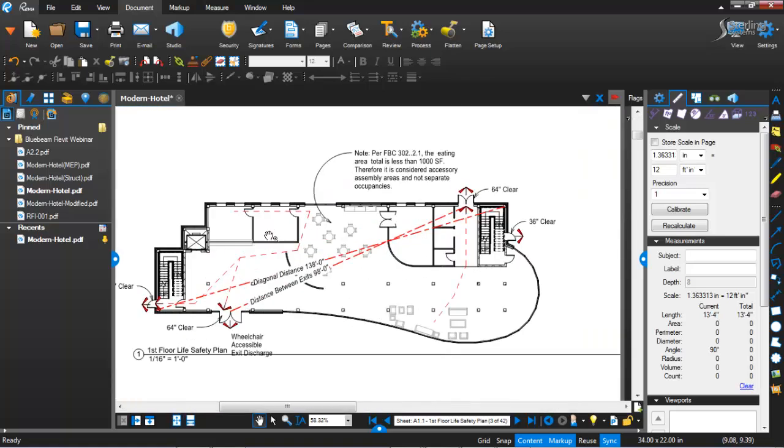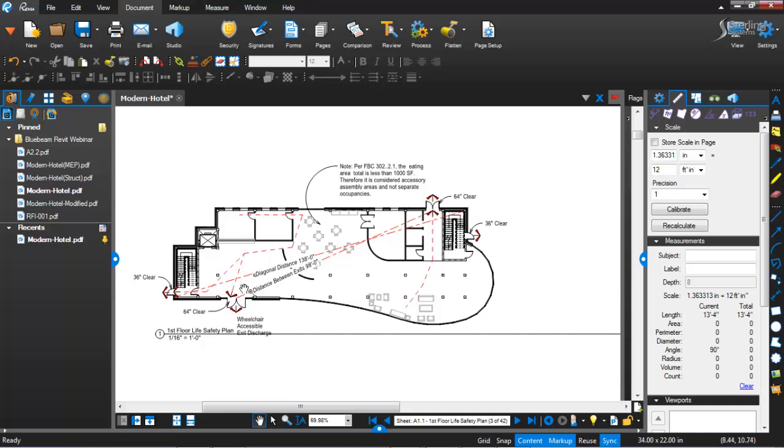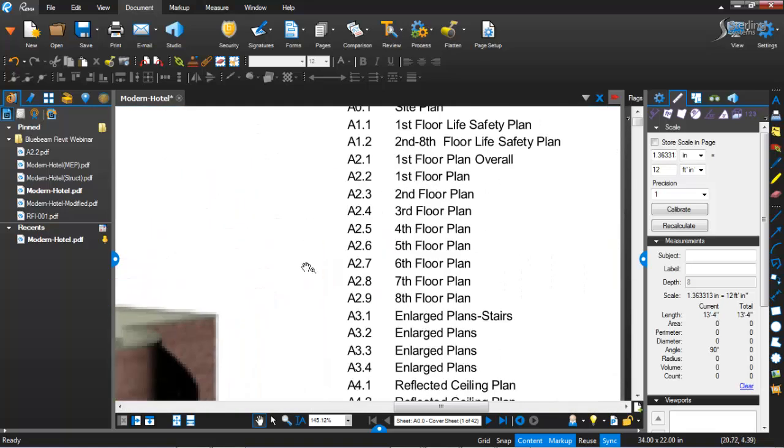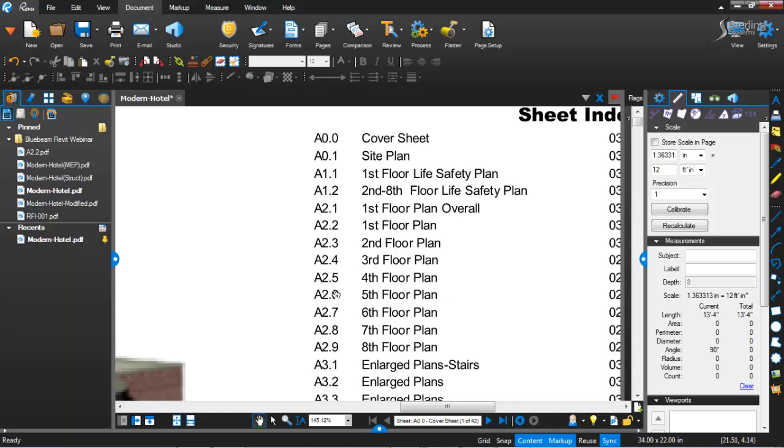Now, what this is good for is actually the section marks and things within the project. So, a very simple command here can take it a very long way. So, I'm going to kind of show you how to do that. And very simple. Let's see which one doesn't have one. I believe it's 2.7 here. There is a shortcut for the hyperlink. And under your markups, you're going to find hyperlink. But there's also a Shift H. I'm going to quickly do that.